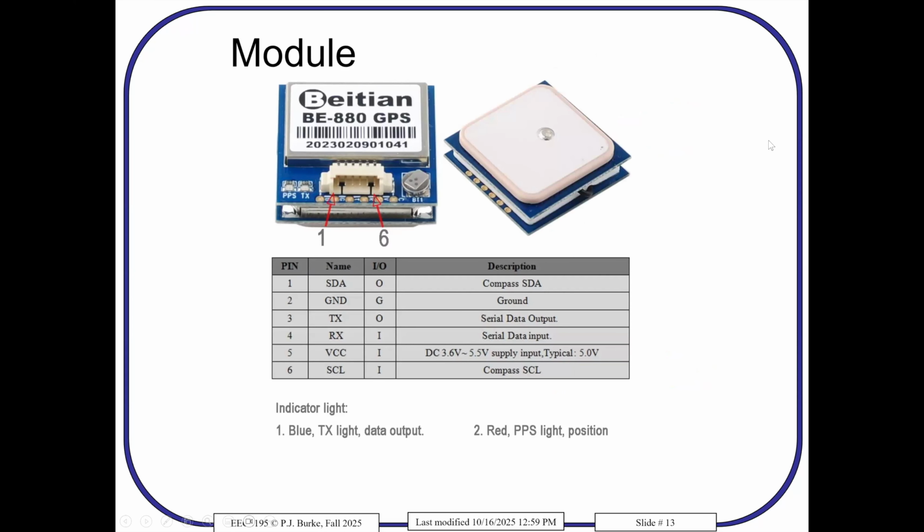Okay, so what is our GPS module? This is what it looks like. This is the antenna. Make sure it points at the sky. Don't point it at the ground. We found in the cabinet somebody had actually had it upside down. I don't know how it even worked. You don't get any lock when it's pointing upside down. And don't put anything over it. Like if you put a tinfoil hat over it, it won't work. Anything metal over it won't work.